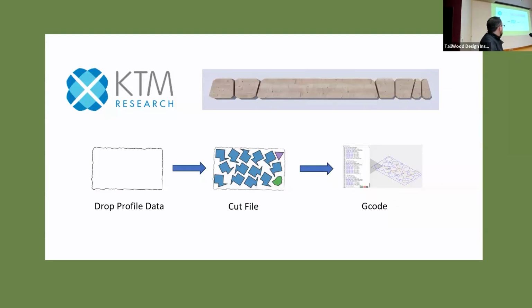They've already helped us with getting the digital files from the part scans, and then the nesting, and that will eventually translate into generating G-code. We recognize that the machining and programming is the biggest time hurdle. So if we can do all that on the back end, then the software can help us nest and optimize, and you really just have to do a final pass check to make sure that overcuts and things aren't getting in the way. So from that, I will pass it off to Chevy and Kyuho.